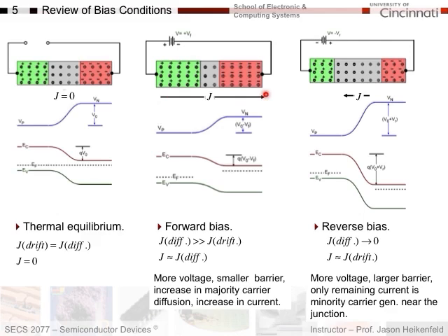And again, we can reverse bias this, negative voltage on this side. That negative voltage is adding to the contact potential, so I need to uncover more charges to contribute to that contact potential so the depletion region grows in width. And I can see that here. I basically put negative voltage, my bands go up, I get a larger energy barrier. The energy barrier is so great that diffusion current goes to zero because I can't get electrons with enough energy over here to diffuse, or holes with enough energy here to diffuse across there, and I'm left with just my drift current, which does not change with voltage because it's limited by thermal generation of electrons and thermal generation of holes over here.